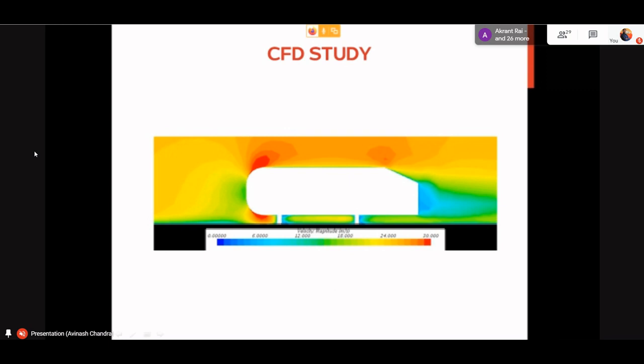Whatever volume you are seeing now is filled with elements, because we have taken the cross section. So we are not able to see, but we can see how it looks on the surfaces. So basically this is called surface mesh, when you define what is on the surface. And then we do the volume mesh to fill the volume with the elements.